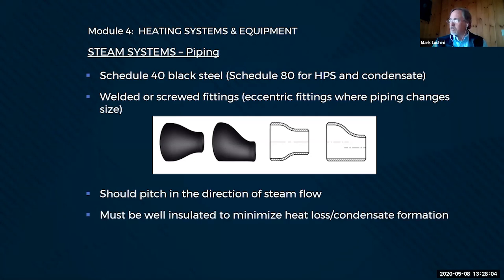And we definitely have to make sure that our steam systems are well insulated, because the last thing you want to do is have condensate forming in your piping. You want condensate to form in the coils.